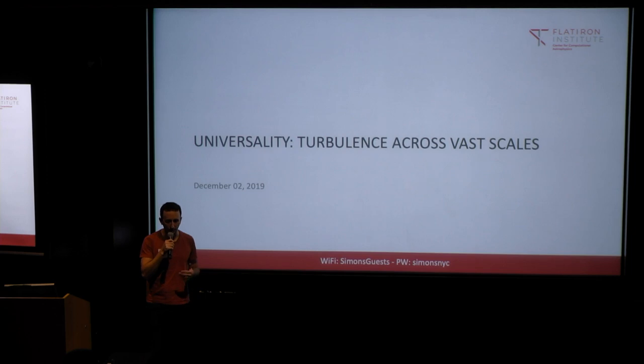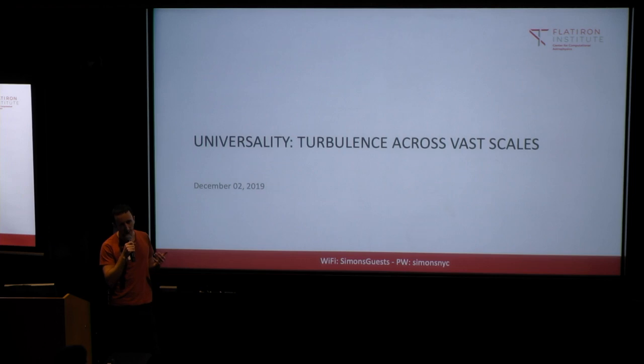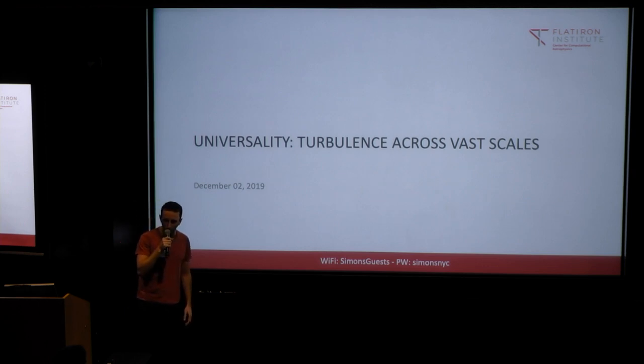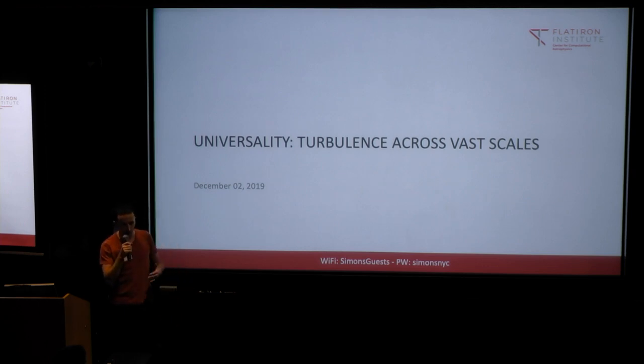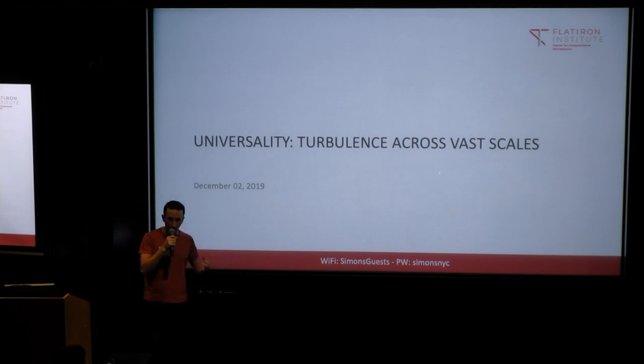And one of the reasons why I think it can be of use to people outside of the rheology community is because in the last 15 years, some studies have shown that there are some parallels between some of the equations of magnetohydrodynamics in some regimes and what's going on in viscoelastic fluids. So you'll see this afternoon, with the talk of Mike Graham, that elasticity, for rheologists, usually comes from polymers inside the fluids. But for magnetohydrodynamics, it can come from the magnetic fields.